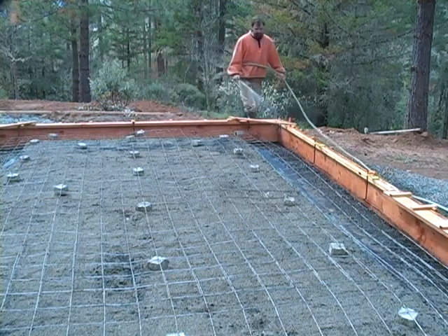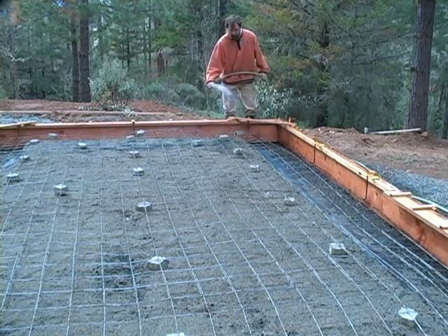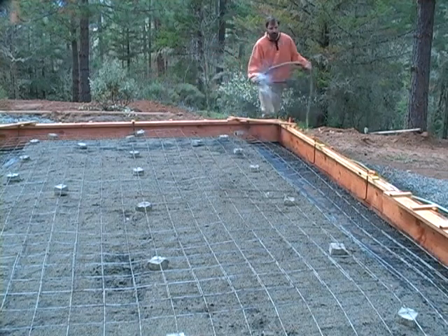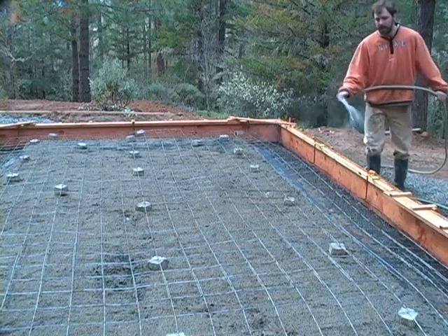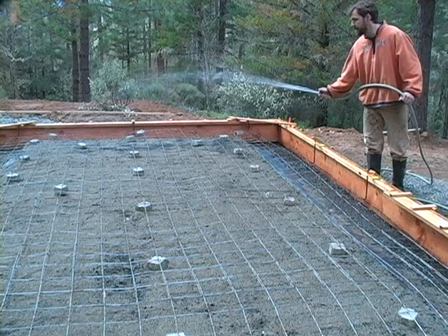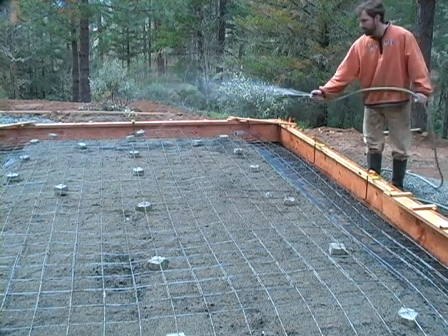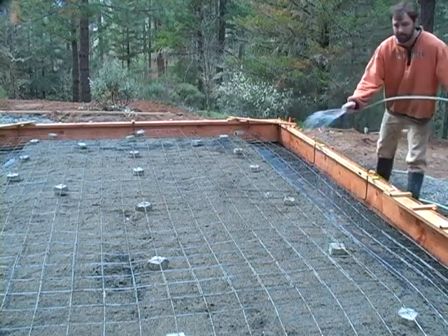On the inside, it serves the same purpose with the inside of the form boards to release them easily, but it also is putting enough moisture content down in the slab itself, without getting it wet, of course, that enables the concrete to cure slowly. If all this sand is dry underneath, it's going to really quickly suck all the moisture out of the concrete and make for a poor curing of the concrete.